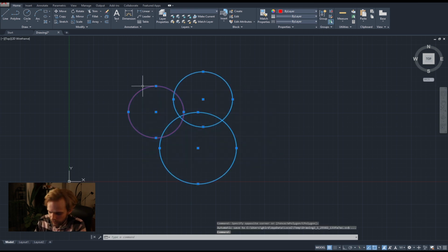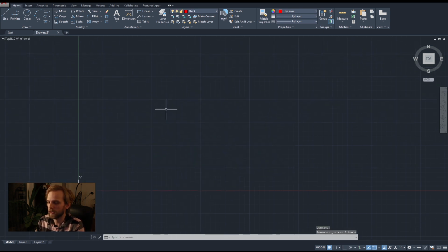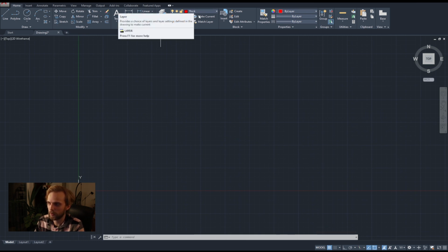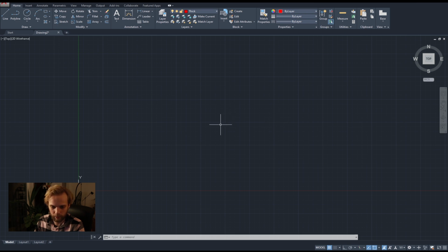So that's that, right? Working with layers, really easy in AutoCAD. Let's start drawing. So I'm going to start drawing in the thick layer with thick lines because I'm going to be drawing a plan, and I'll start drawing from the walls, right? Or rather from the section of the walls. So the plan is cut at 1.2 meters, so that you are cutting through windows above the tables and whatnot. So it's like a locked number.